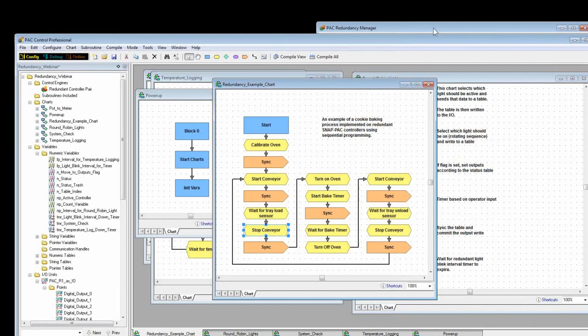I can tell everybody is thinking these through because they're coming up with all kinds of permutations for you here, Benson. That's fine. What happens if the crossover link fails for some reason and you get a synchronization error? Same thing. If the link between the two controllers is lost, then you don't have a redundant system anymore, but you still have a functioning system.